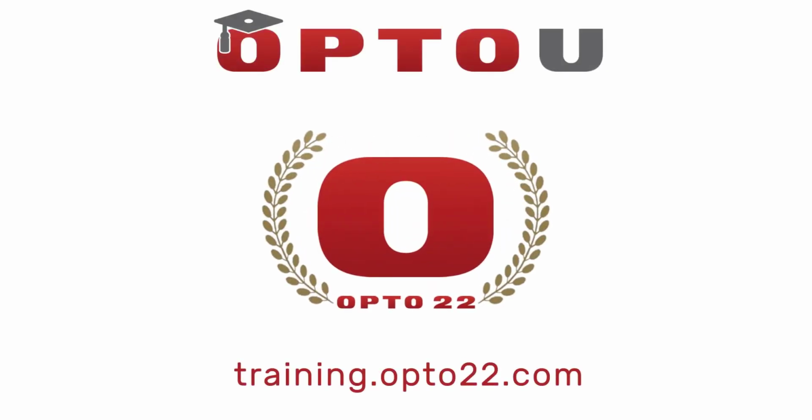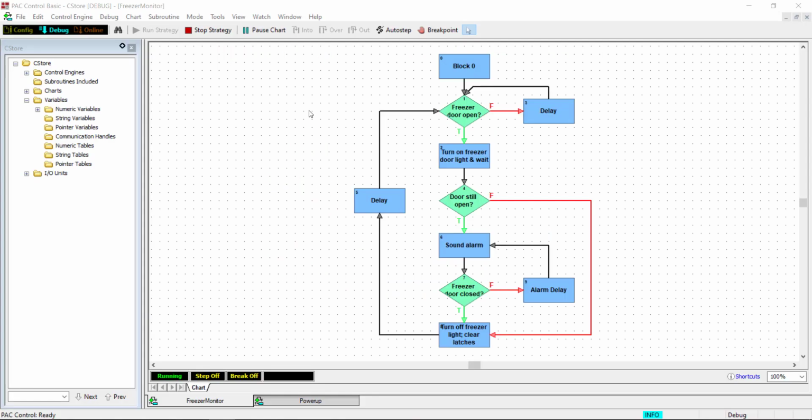In this tutorial, I'll focus on using the debugging tools in PAC Control. You've downloaded and run your strategy. Now let's see how to use the debugging tools in debug mode. We can see this chart is running here in the chart status window. But how do we know which way the logic is flowing?